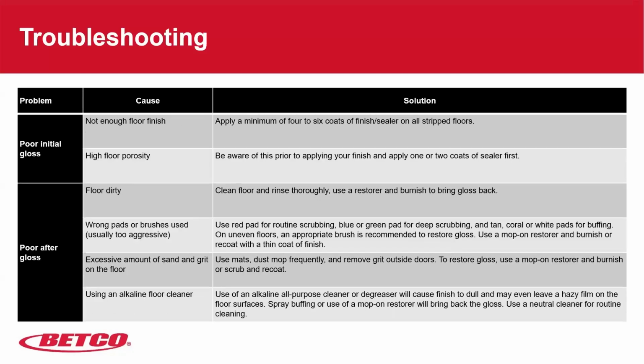We also find there are a lot of challenges where we don't properly strip the floor. We do a fairly good job, but there are patches and splotchy marks where we've left finish that has absorbed stripper. Then we put a new coat on top and it looks splotchy, because there's stripper in that little patch of finish left on the floor. You put finish on top, and that stripper goes to work again and starts stripping out the finish you tried to put on top, when you're trying to make it look nice again.